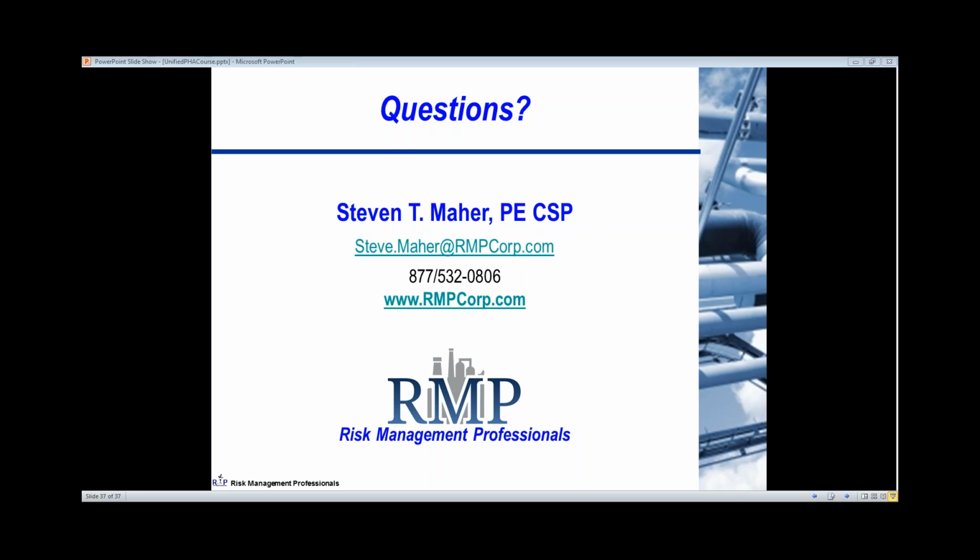There's an inconsistency in the industry around how many credits to take for BPCS. We limit it to only 1 credit for BPCS. What is your take? Okay. If you take more than 1 credit, you should be very, very careful. The key issue is common mode failures. BPCS type equipment can include common logic solvers. There may be other elements in common that aren't apparent from the P&IDs. So typically, you'll want to make sure that your instrumentation person on the team is on board.